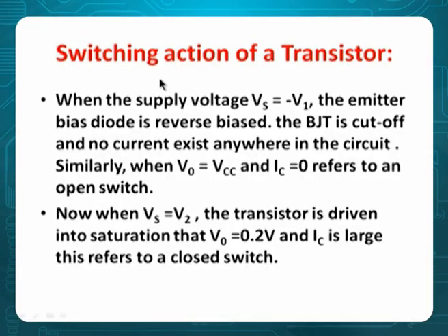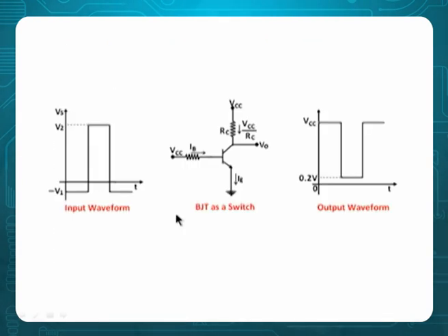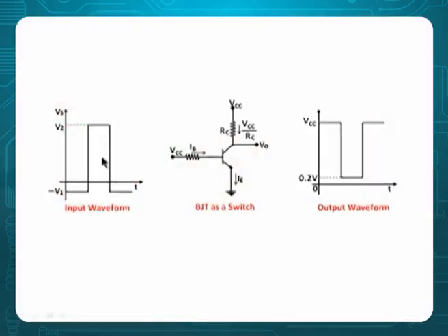Then suppose I give negative voltage to the transistor, that is off. If I give a positive voltage here, that is on. And let me show you here. This is a transistor. In the earlier example, I gave high voltage and low voltage separately. Now I am giving a pulse. First it will act as a low voltage, that means the transistor is off. Then it will act as a high voltage, so the transistor is on. And low-high became high-low, which is generally called an inverter.